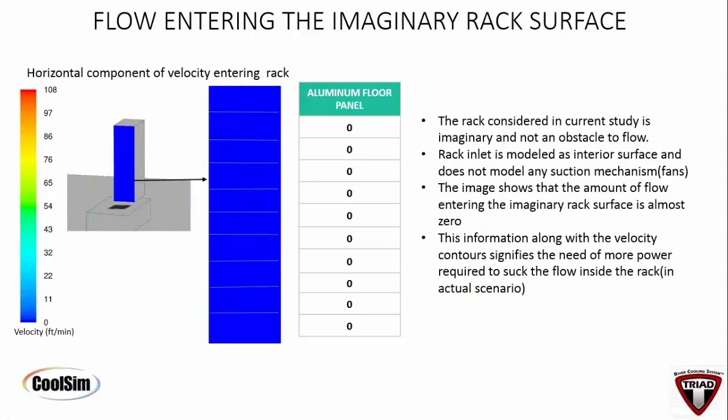Yeah, it's actually, we're part of National Science Foundation studies as well, and they call it entrainment, that the air is moving so fast that it's actually enslaving the server fans trying to pull air in, that they're having to run at full bore, attempt to pull anything in, and what's happening is pulling heat back through the face of the server. It's just moving too fast. Yep, yep.